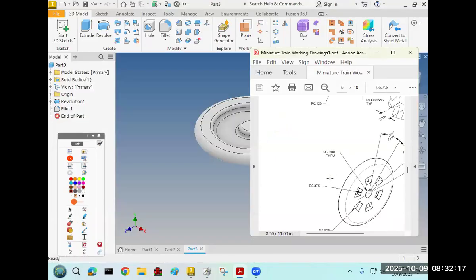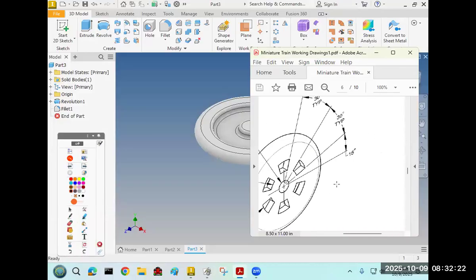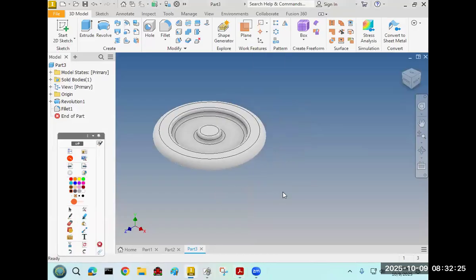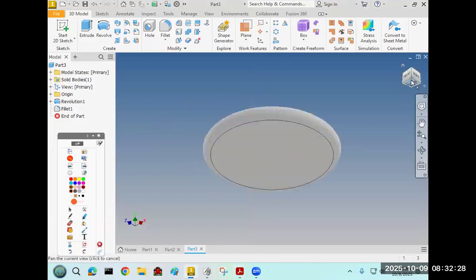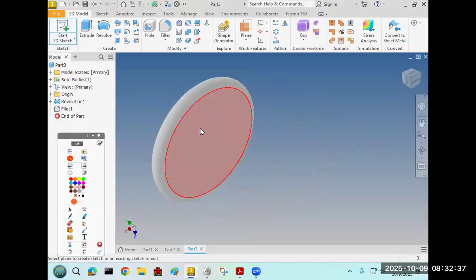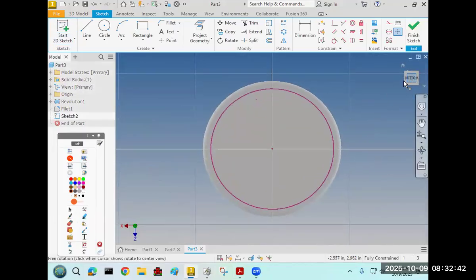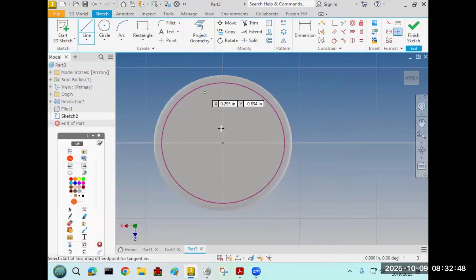All of this is going to be done on the back because it's flat at this point. So it's a lot easier to handle. And so let's look at the back, I guess, like that. It's not super critical the way you're looking at it, but we're going to sketch on the back. When you're looking at it, if it says bottom, whatever, make it so that you can read it. And our first line from the center, I'm going to put it past everything so it doesn't interfere. It just needs to snap to horizontal, however long.